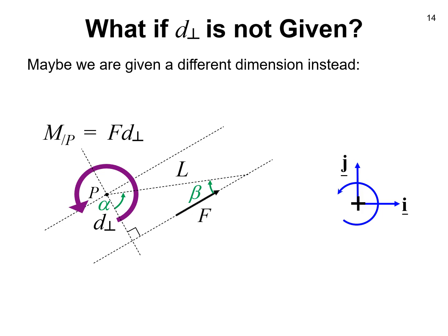Also, in some cases it might be useful to slide the force into another position, again along the same line of action. And in this case, we'll decompose the force in components relative to the line that we're given, in this case relative to the line along L. And if I draw that second angle symbol, I think it's clear that's the same as the angle beta.